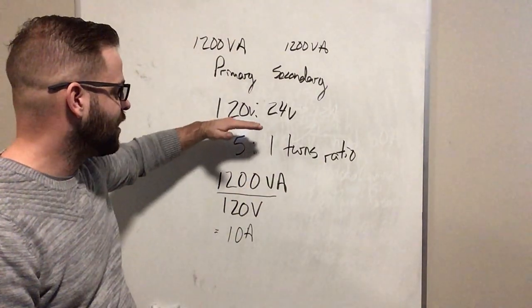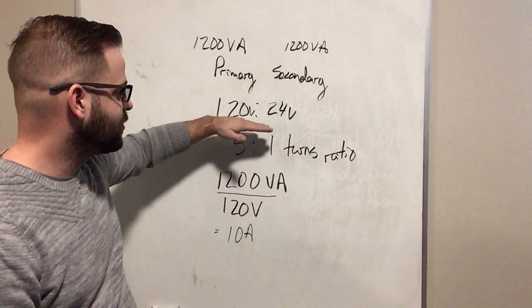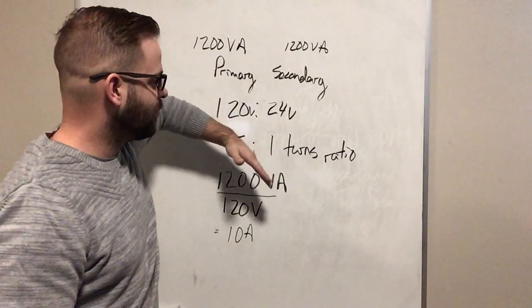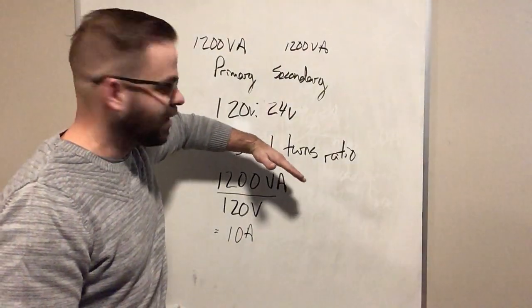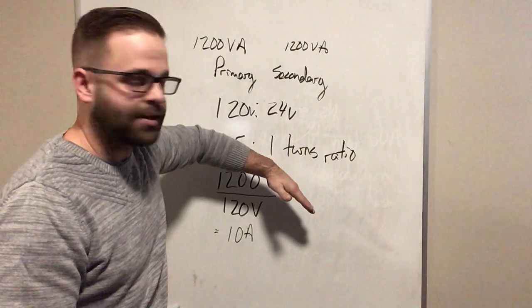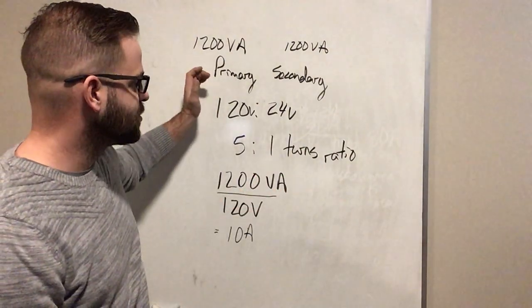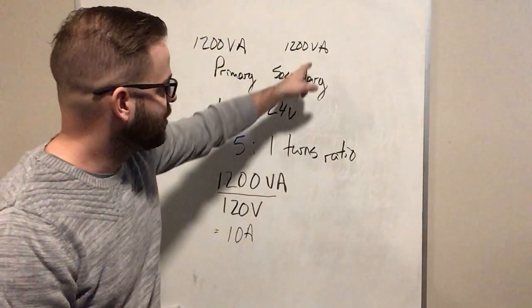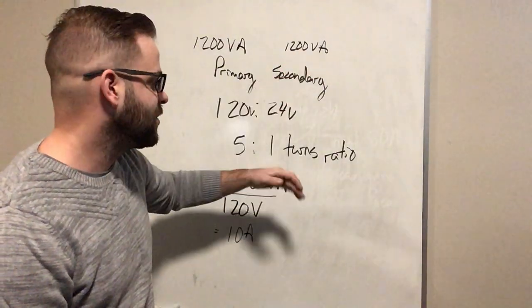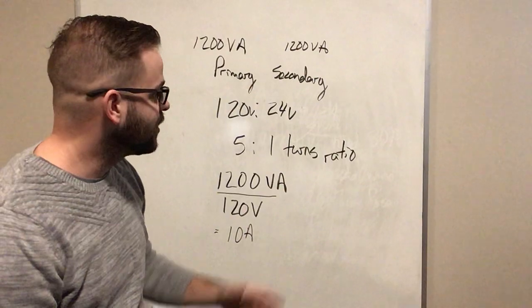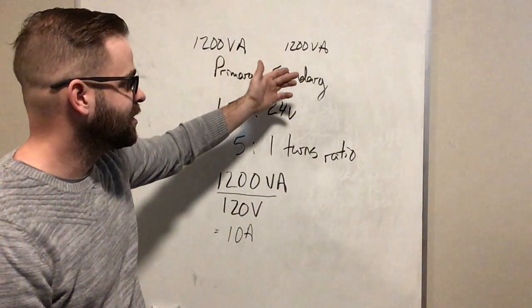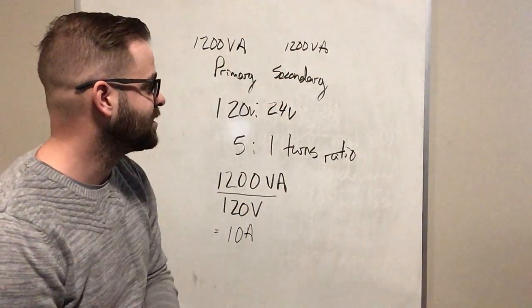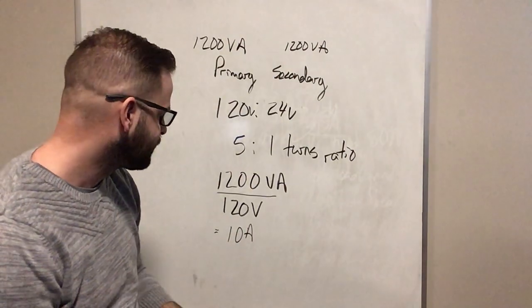But what I've found is that my voltage has gone up on one side, and my voltage has gone down on the secondary side. Well, if the voltage is up on one side and then ends up going down, but my power remains the same, that means that something else has to go up. And the only other thing that can go up in this case is my current.